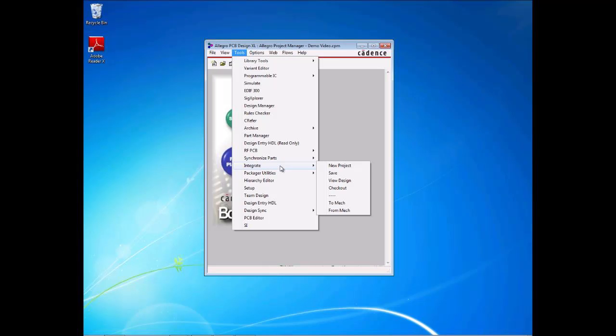This step will connect existing structures in PLM with the project. Out of that, metadata information, like the identification number, can be found in the project parameter list right from the beginning. Last but not least, the feature New PCB should be mentioned. In the beginning of that demonstration, we created a new project with a schematic drawing and the related PCB technology. There might be the case that the PCB technology is not known right from the beginning. Therefore, the schematic engineer might start only with the schematic and add the PCB with the feature New PCB later on.